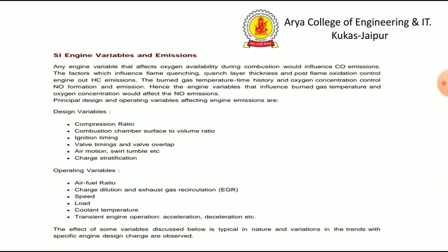Engine variables that affect oxygen availability during combustion would influence CO emissions. The factors which influence flame quenching, quench layer thickness, and post-flame oxidation control engine-out HC emissions.